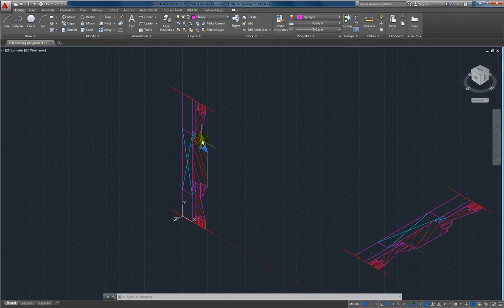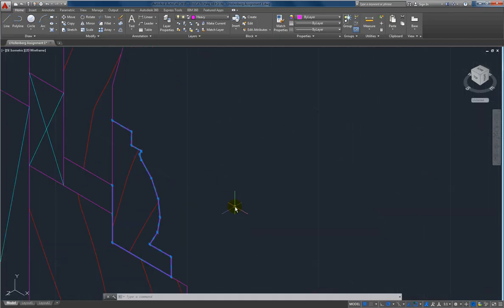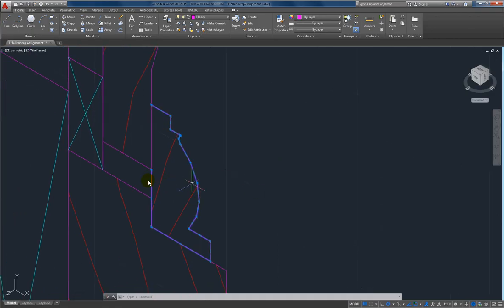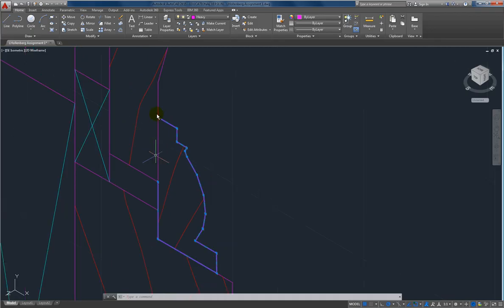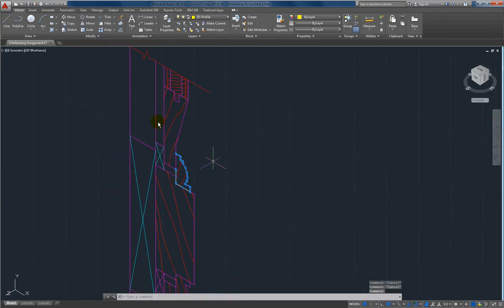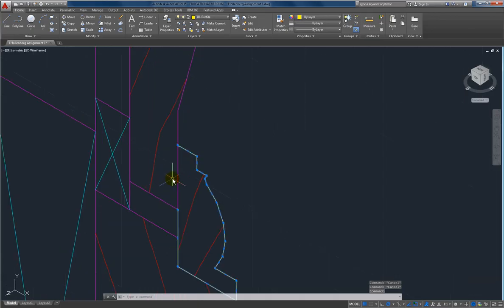No, they stay. But when I extrude it, I want to make sure that, like I can see right now by selecting this, this is not a closed P line. Right? There's a big gap here. All right, so this is where I want to spend some time and fix this. So if I select this, I can go to under Home. I can switch this to 3D Profile. All right, so now it's yellow. And this also gives me a way to understand what I've corrected, what I haven't corrected, okay?